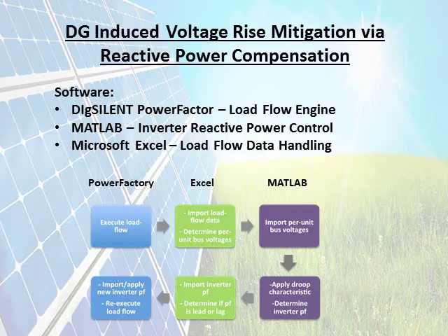The network model in PowerFactory consists of one distribution substation with a 400 kVA transformer. The substation has 2 LV feeders and supplies 88 customers, 27 of whom have solar installed at their house. The combined rated capacity of installed solar is 86.8 kilowatts, which gives a total DG penetration of 21.7%.